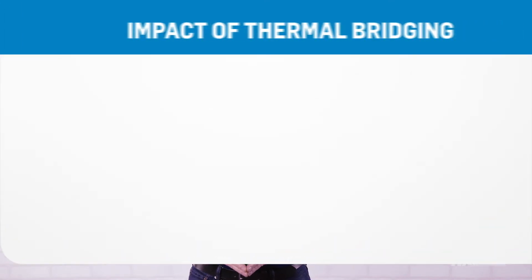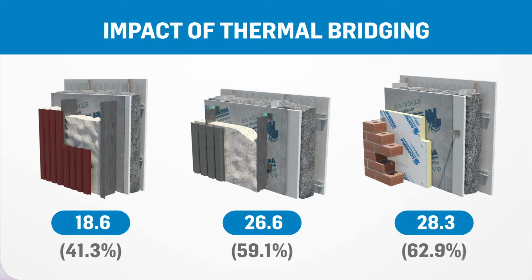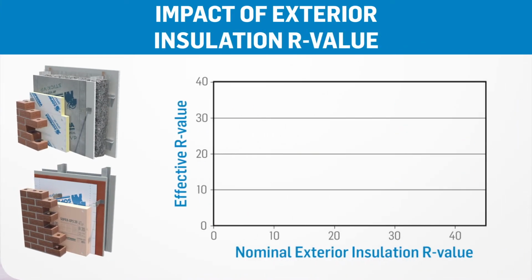If we compare the three split insulated systems, we see a relatively modest increase in performance. Looking at percent retention of insulation nominal R value, R45, for the three assemblies, it ranges from 41% for the first assembly to 62% for the best performing. The percent retention results are much lower here than they were in the former trio. We'll shortly see why.